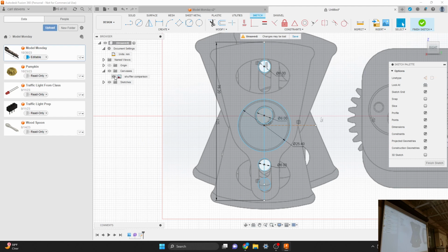But anyway, now that you've got that line drawn, you can use your mirror tool. I would try to pick on the edge of the circle as opposed to the middle of it, because you can just mirror the center point of a circle as opposed to the outside ring. So you go for the outside? I would go for the outside ring, yeah. Because when you do the outside ring, you actually get both. Hey, look at that. There we go.